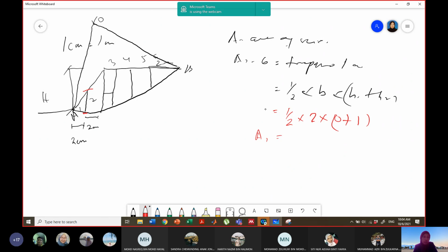And then the next important part is the W. Where is the W? The W is located at the mid of the slice width. Okay, for example here, if you consider all the slices in trapezoidal shape, this is the trapezoidal. So let us take the centroid of this shape. We can have that the W is acting at the half from the B.